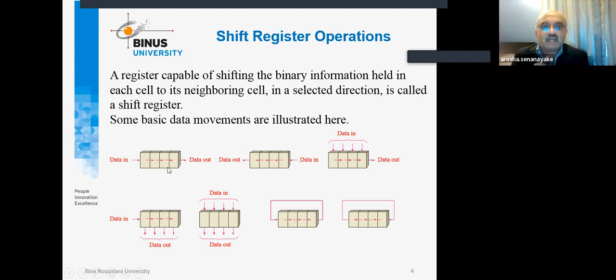So then you can see that when it comes to D-type flip-flops, each box here, each D-type flip-flop can store only 1 bit at a time. So you can see here we have an arrow called data in. The idea is that these boxes are connected through just a single cable. One cable means that really data transmission is 1 bit at a time.